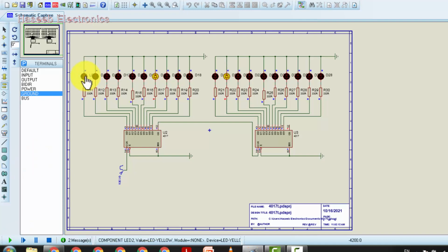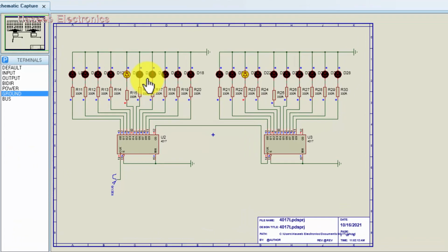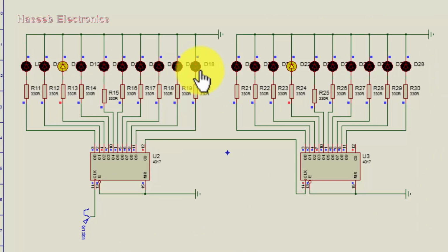Now we can see the first set, when it reaches the end, it will give one carry pulse to the next stage. Now this counter is slow. We can connect more sets, next outputs. Every carry will drive the next circuit, but the frequency will be divided by 10. After each 5 cycles in the first stage, the next pulse will go high, and then for the next 5 cycles